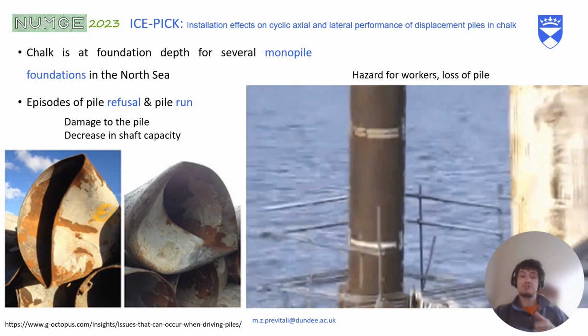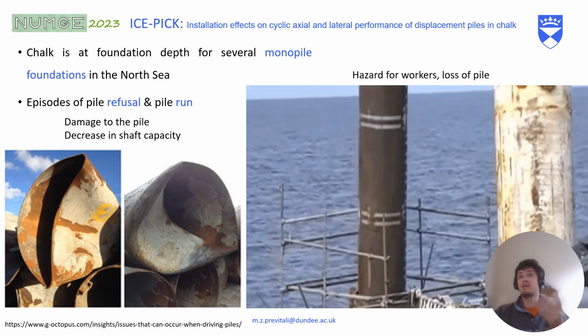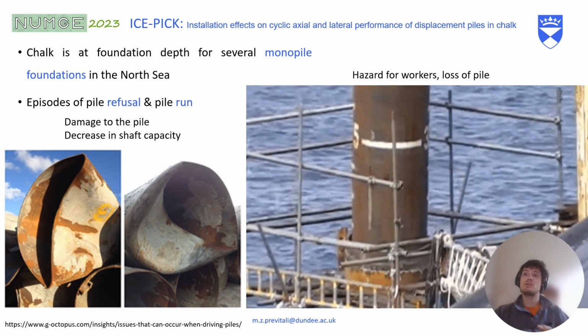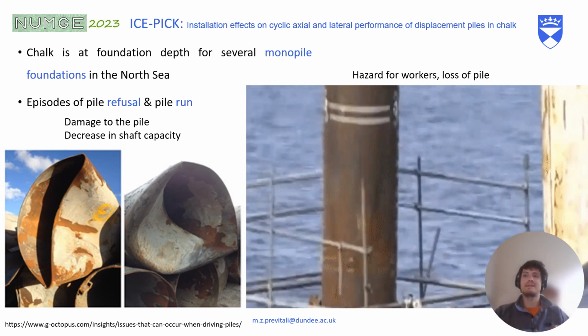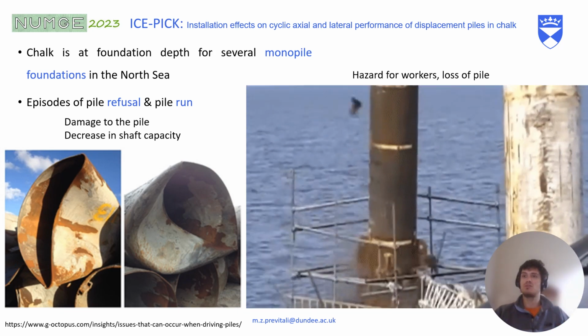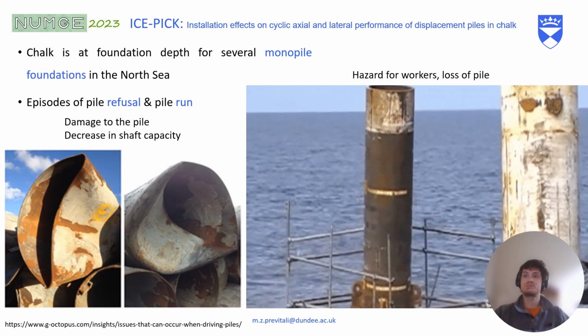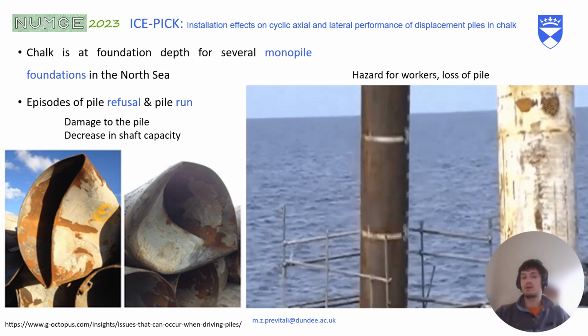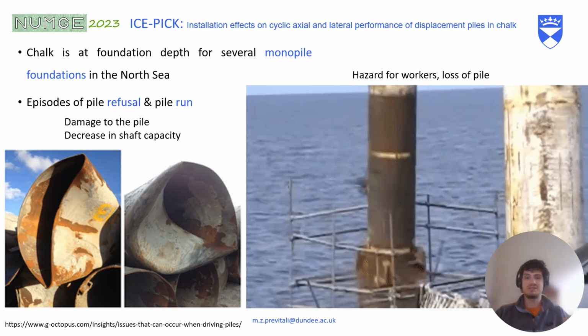And then you have episodes of pile run, as you can see in this video, where you can have actual loss of the pile, meaning the pile just gets self-installed or drops into the chalk under its own weight and is no longer serviceable because it just goes underwater.